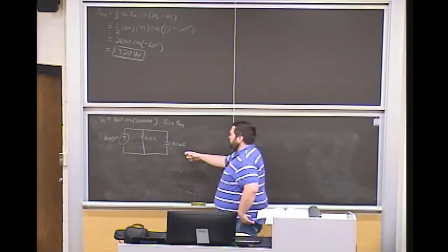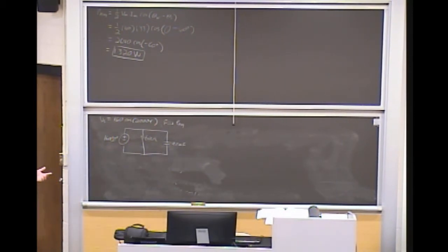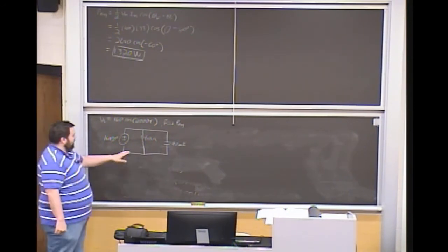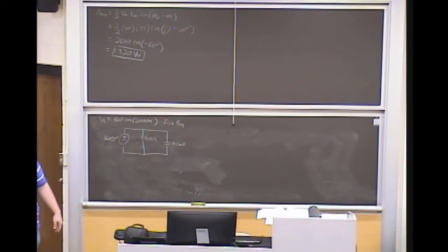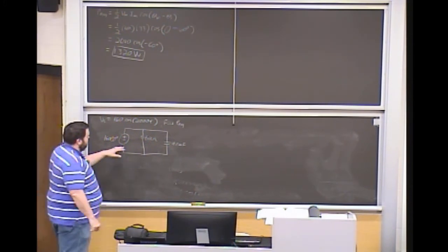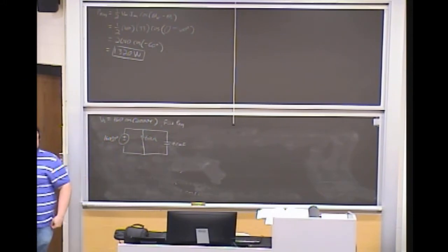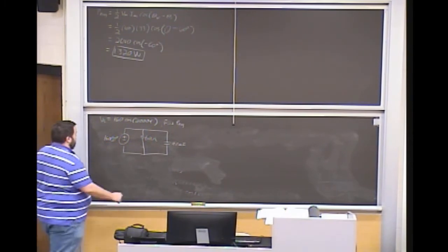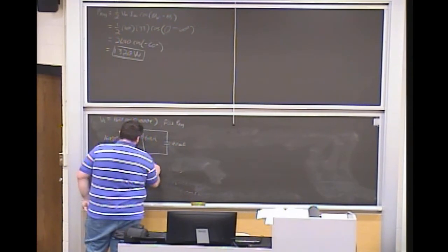Well, the load is both of these. So there's a few approaches you could take here. The first approach, which actually is a little bit longer approach, is to go about figuring out what is the impedance equivalent of those two loads in parallel to one another. And that's always a way that you can go, is you can always say, okay, let me figure out what all these things add up to be in parallel just using that reciprocal relationship. So you could figure out ZR is just going to equal 60 ohms.